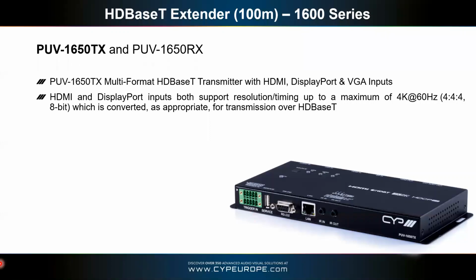With your LAN serving on these 1600s, it's quite normal to put the LAN into the RX, and so the LAN port on the TX can be locally used. So you put the LAN into your RX, and then you have it available at the TX at the meeting room desk if someone wants to hardwire into the system, if you're giving a big presentation and there's lots of data and you don't want to use the Wi-Fi.